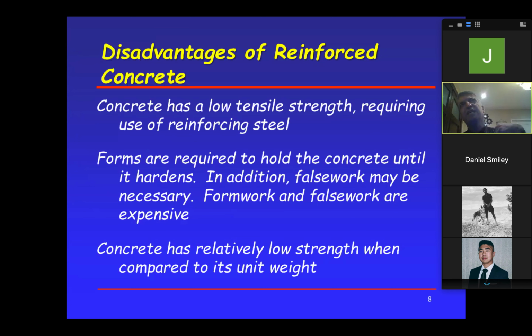I'm sorry. When I say steel, there's two types of steel, so we don't get confused. The steel we're using here is reinforcing steel. The other steel that we build buildings with, we call it structural steel. So I'm going to differentiate when I speak. So if I'm doing a structural steel building, I bring a column, you can just stand it up vertical and then put the bolts down. But then if you are doing a concrete column, you have to form it, put the reinforcing steel inside, then pour that. Okay? So that's an advantage to the structural steel, disadvantage to the concrete.